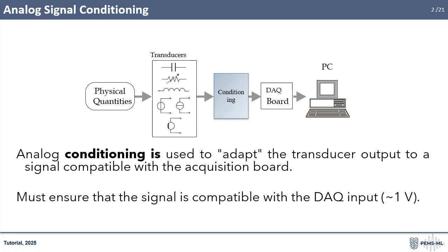So, the analog sensors and transducers give a relationship between the quantity of interest and the variation of an electrical quantity, such as a voltage, a current, or an impedance. However, the digital conversion of an analog signal can convert input voltages to digital waveforms. Therefore, it is necessary to have a conversion block between any electrical quantity and a voltage that can be measured through a data acquisition board. This block is usually called the analog signal conditioning stage and represents the electronic circuitry that converts an input electrical quantity to a low voltage signal of the order of a few volts.